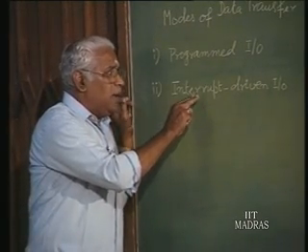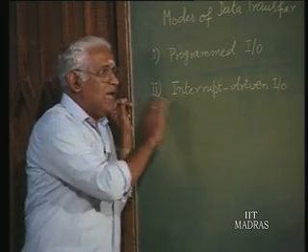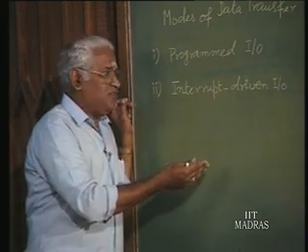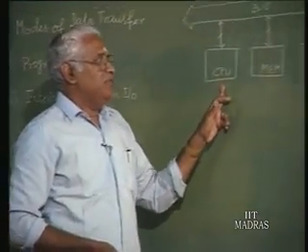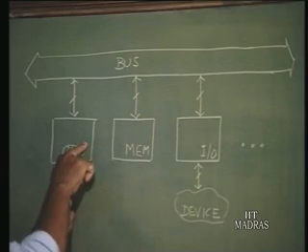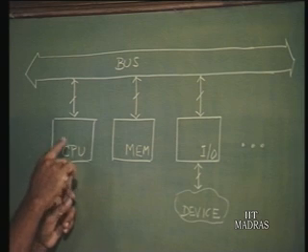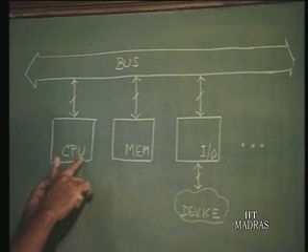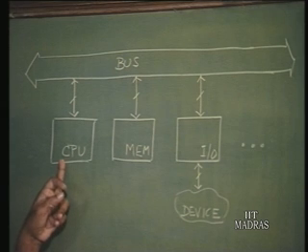In that process there is some delay. Why? Because after the device has been serviced, the CPU must switch back to the main program, is it not? The CPU is doing something, the device when it is ready is going to indicate and interrupt the processor. The processor activity is interrupted, then it is going to attend to the interrupt service for the particular device which is interrupting.